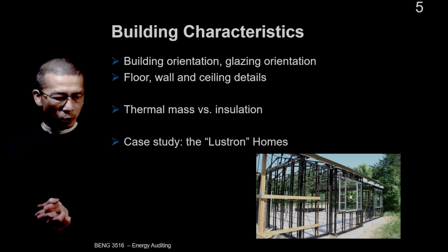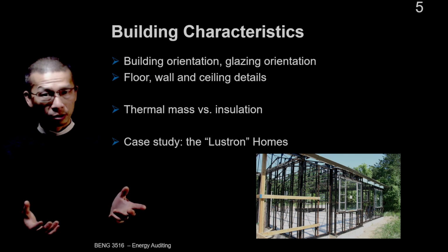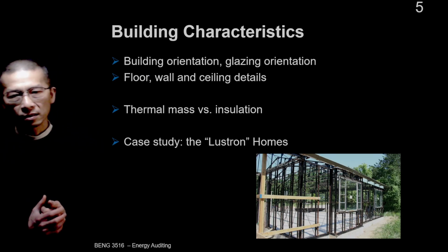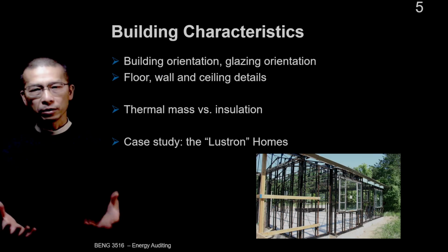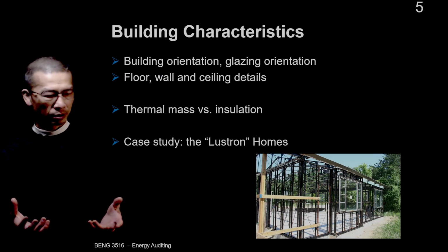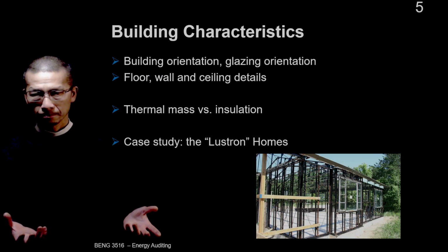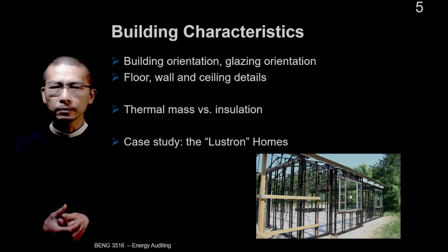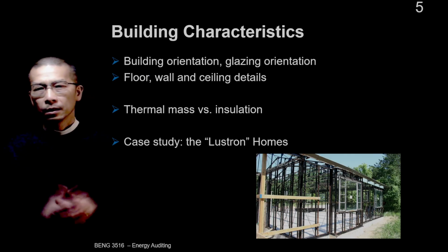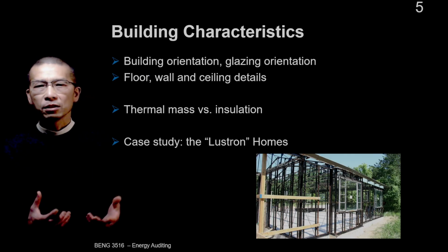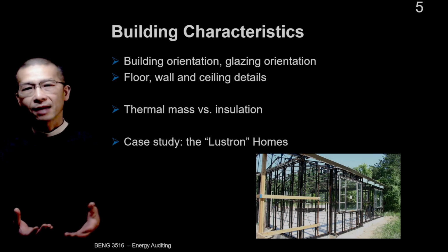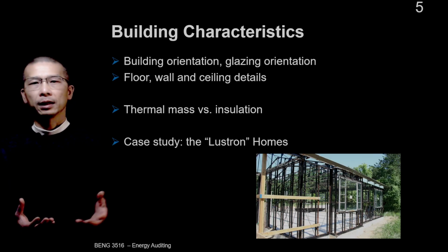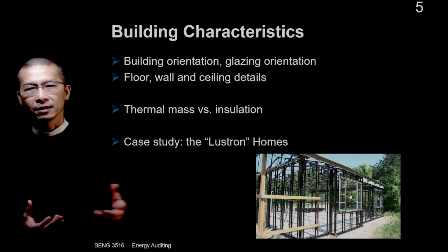Okay, thermal mass and insulation. So one concept is important here, right? Thermal mass, like concrete floor, versus insulation, like fiberglass. Insulation slows down the rate of heat transfer. Thermal mass acts like a battery, right, that can store heat and release it later.